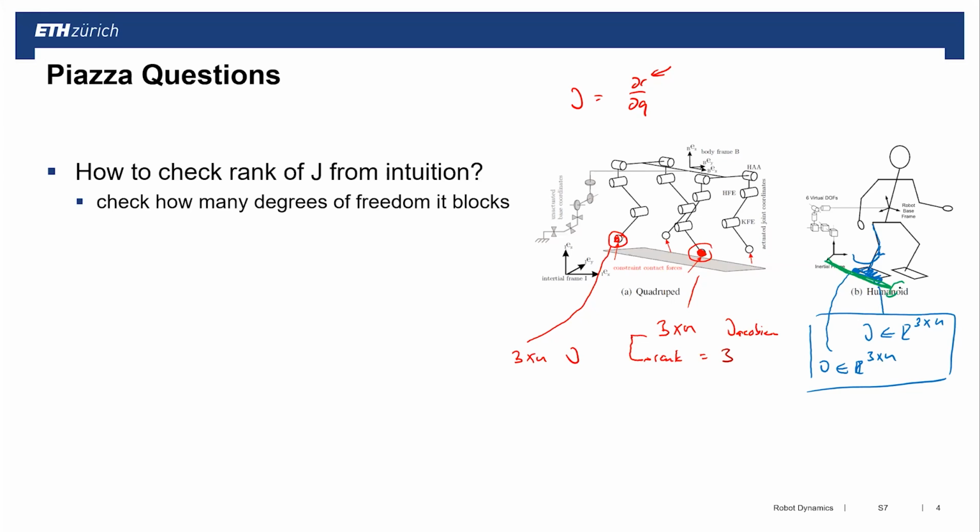And that means we have a linearly dependent constraint. We have 6 dimensions in the J, but only 5 independent dimensions, which means that we have 1 internal direction, which is the distance between these 2 points. And we're going to see the exact same thing then also if you're analyzing the rank of this stuff for the quadrupedal system in the example that we have here.